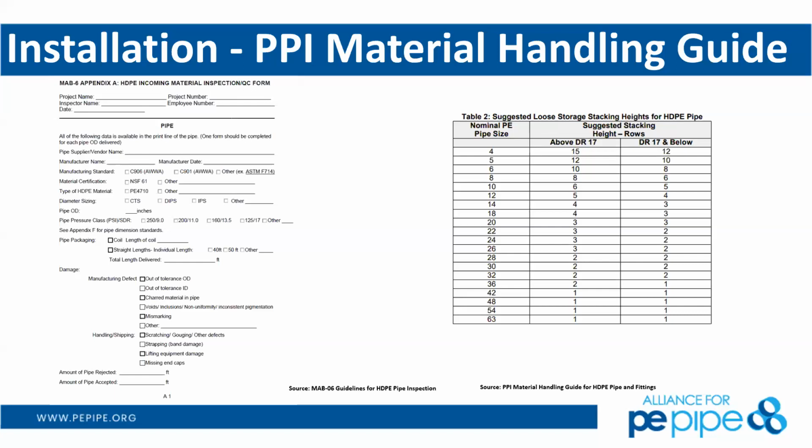If you want to do on-site damage inspection, you should do that at the time as well. Remember, polyethylene does have a 10% allowable scratch depth. So while no pipe should arrive on a job site with scratches and gouges, if it does from handling in the field, a 10% allowance means you don't have to do anything with it. You can simply go on once you measure that 10% of the wall thickness of the pipe.